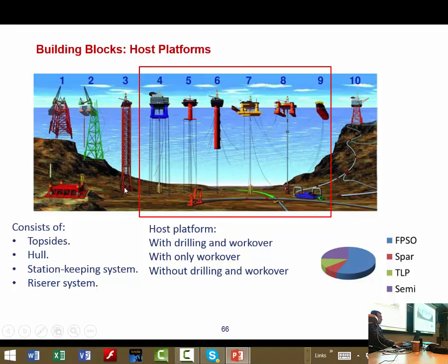But here, when you go to some water depth, as I mentioned earlier, the maximum water depth that fixed structure solution or jacket type structure have been used up to now is 420 meters. But also we have a gravity-based platform which have been used into 600 meters, like Troll A. Yes.